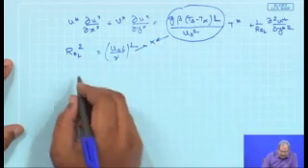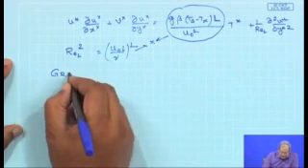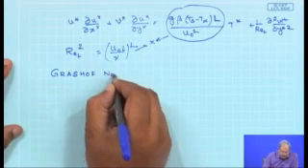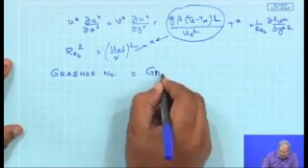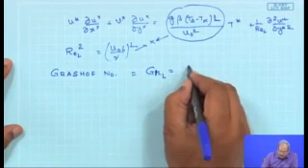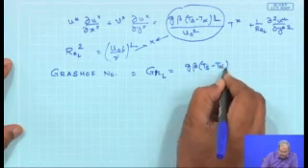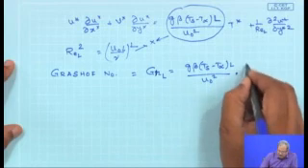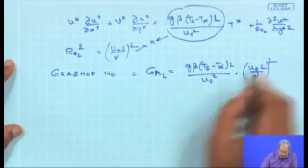Reynolds number square, and what you would get is a new dimensionless number which is known as the Grashof number, which is denoted by Gr based on the length, as g beta (Ts minus T infinity) L by u naught square into u naught L by nu, which is Reynolds number square.